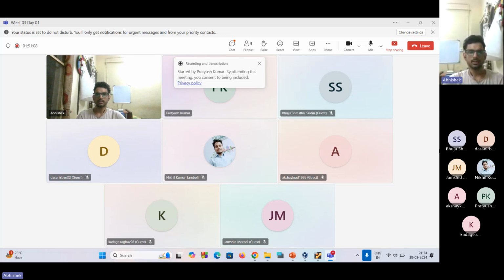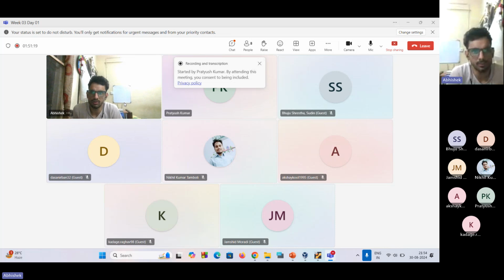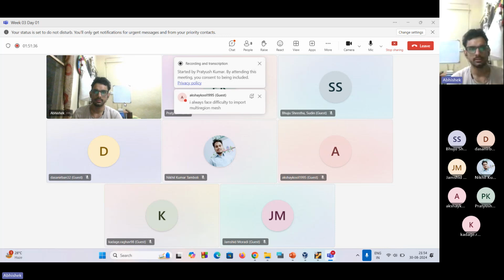Yeah, actually you can import the mesh using ANSYS Design Modeler geometry or mesh. You can also make geometry in Gmsh, Gambit, and a lot of software. You can always import, and it is very simple. Today is the basics of blockMesh. When you have to import a mesh, you first have to understand how to define the patches in ANSYS Design Modeler or Gmsh. Then converting it to OpenFOAM is very simple.